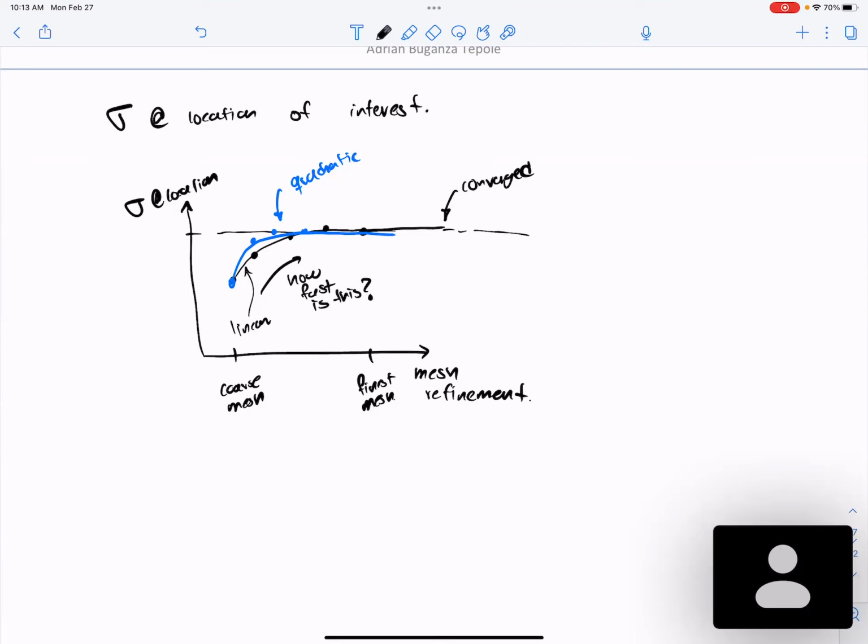And so practically speaking, there's a trade-off, because as you can see, for the quadratic shape functions, you could argue why not just use quadratic shape functions from the start. And the trade-off is a couple of things. One is quadratic shape functions take more function evaluations because you have 3 shape functions per element. You cannot just use 2 Gauss points. You need to use 3 or 4 Gauss points to integrate them. So overall, you need to do much more computation. For linear elements, you need to do less computation.